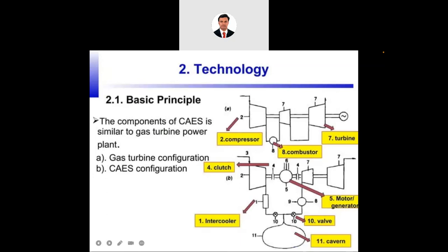Generally, there is a simple gas turbine. Okay, it will have the compressor, then the combustor. Again a second compressor or combustion chamber, the first turbine, and there will be a second turbine. So first of all, what happens in general working? We take air from the atmosphere and compress it, and it passes through the combustor where combustion takes place. After that, it passes through the different levels of the turbine.